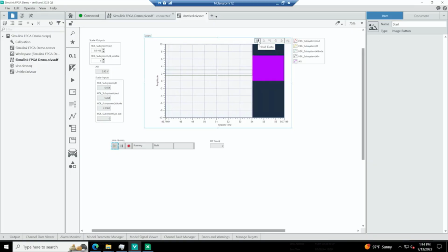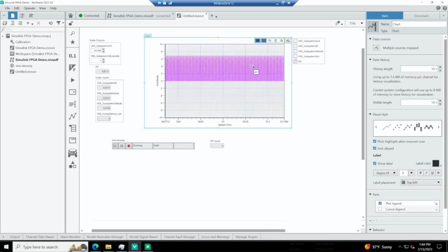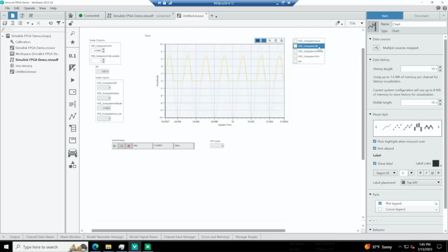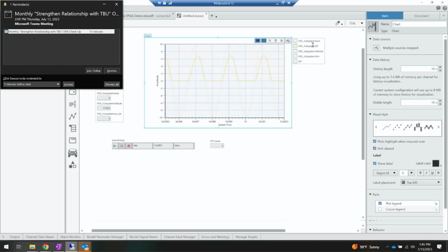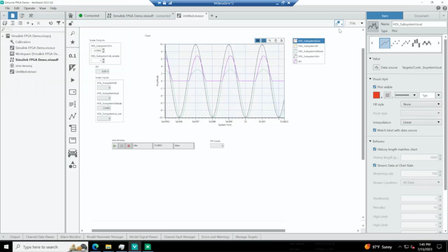It's a little bit overloading the screen here, but what I can do is pause that, and let's zoom in on the response here quite a bit. And what we can pretty quickly see is this mirrors a lot of what we were actually seeing in Simulink. So I can see this is my sine wave voltage input. I can actually then receive these current values, which matches what we'd expect from our Simulink response. In addition, as I mentioned, I had that loop back for one of these here that I'm measuring back